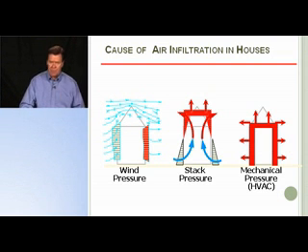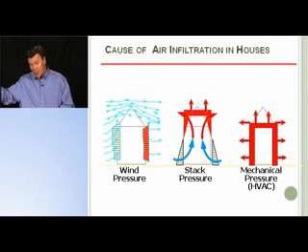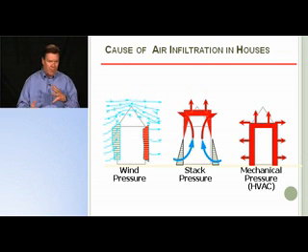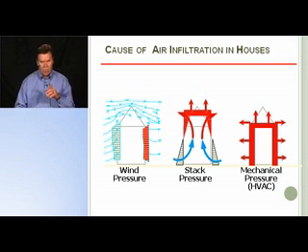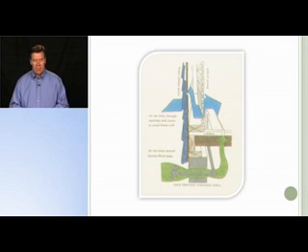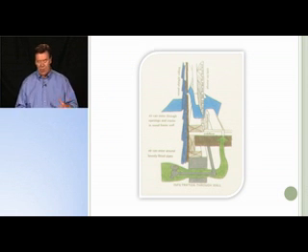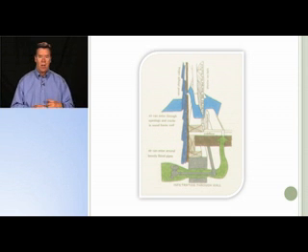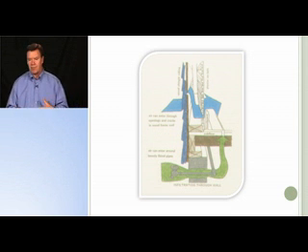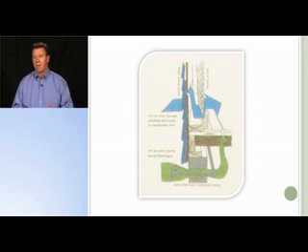And then another mechanism that impacts heat transfer are mechanical systems. In other words, when we have fans in our blower motors and our furnaces, and we have our ductwork located outside of conditioned space, that can create pressure differences that cause air to infiltrate in. We'll talk a little bit more about that later. But when we talk about air infiltration, this is really what we're seeing. It's just air coming in through all the cracks and gaps around penetrations, plumbing penetrations, leaks in the building envelope.